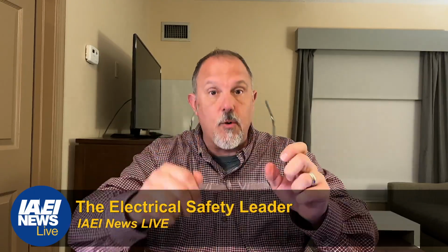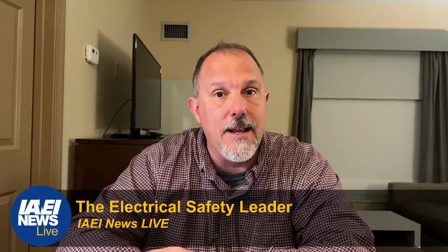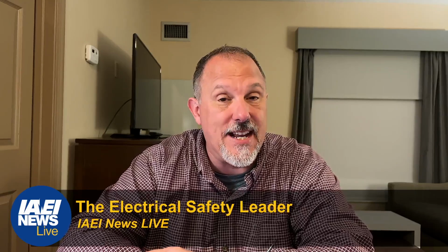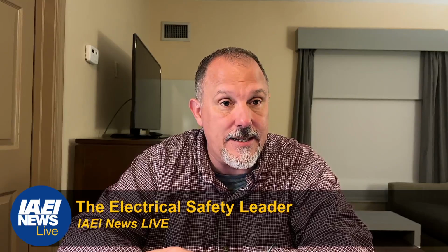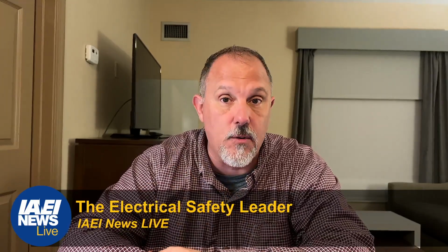The crawl space requirement. Remember, we had a requirement for the light that's in a crawl space to be GFCI protected. That's in 210.8(C). It did not change this cycle. It's still there. We still don't have a definition of a crawl space. You'll know it when you see it.